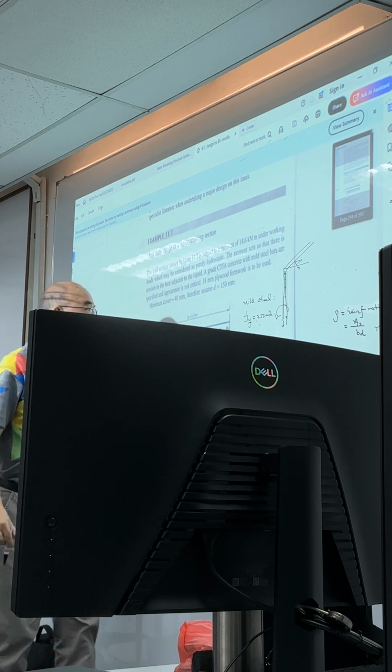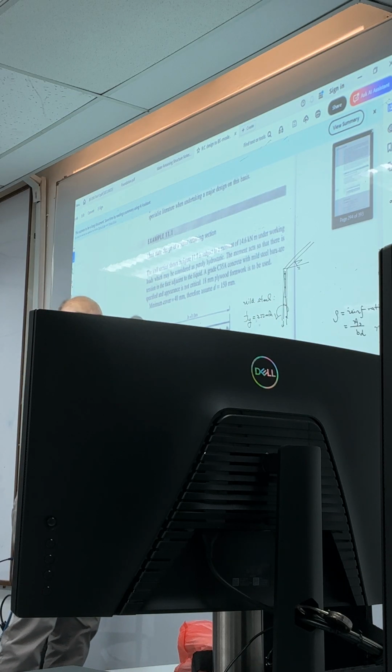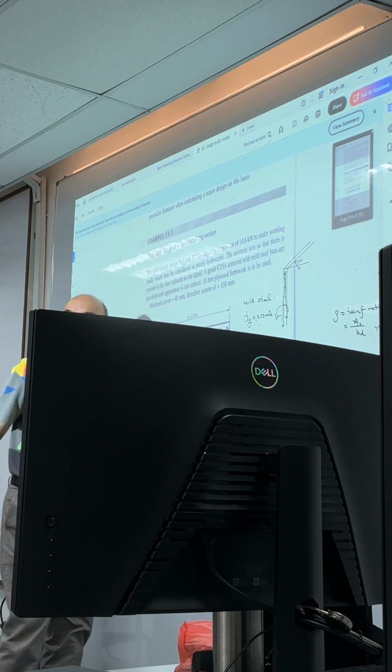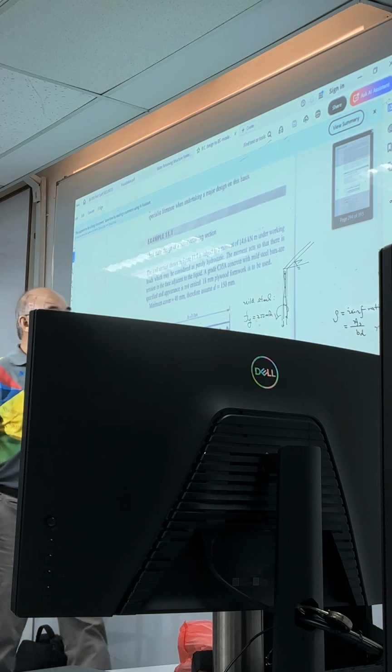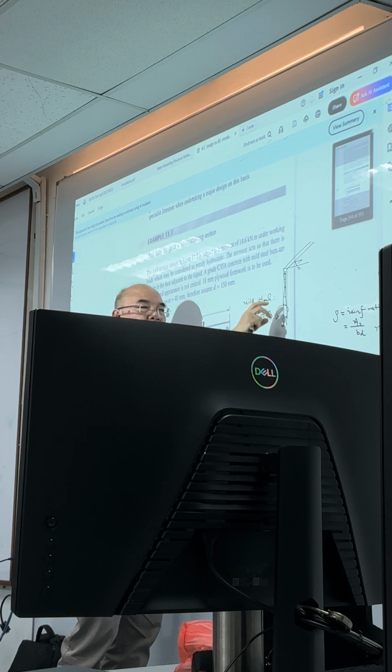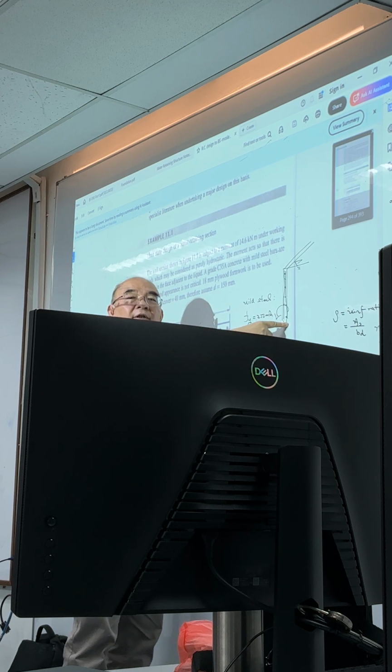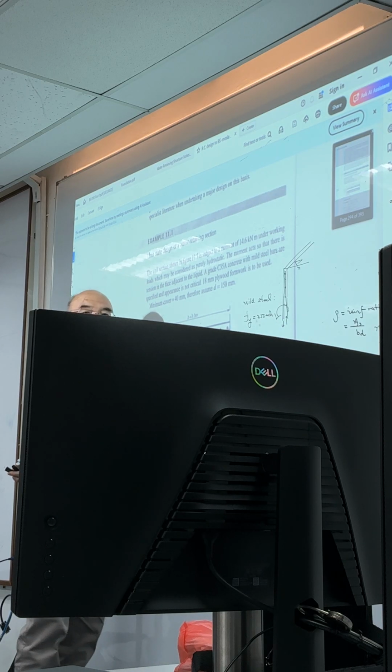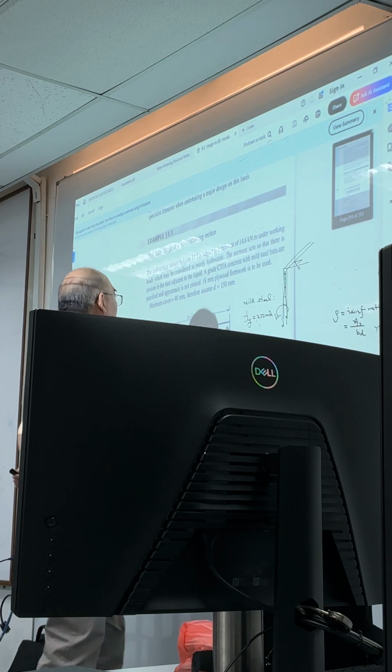So this is the vertical reinforcement because this is looking at the plan view. This is the horizontal reinforcement. So we are going to look at the vertical reinforcement first because our moment is like this. So part of our vertical reinforcement is to carry tension. In this case, this is carry tension.